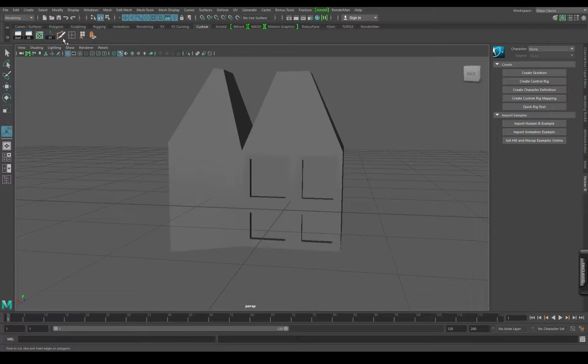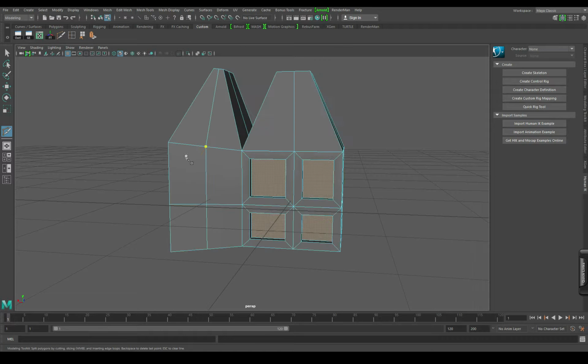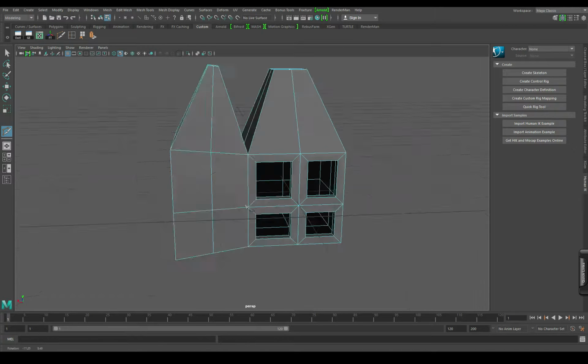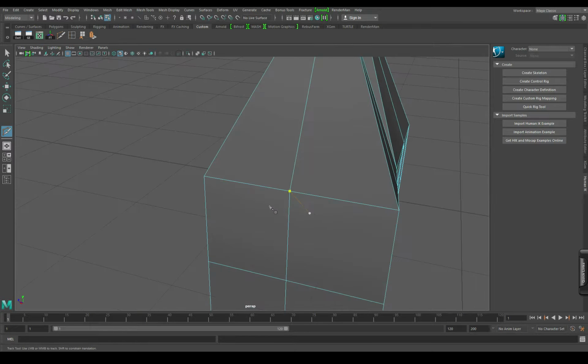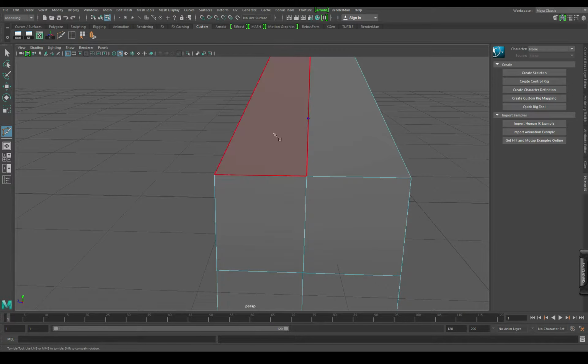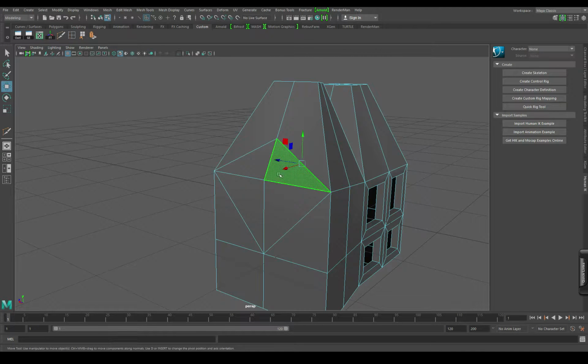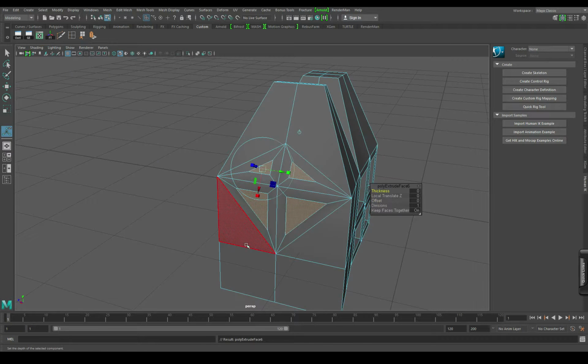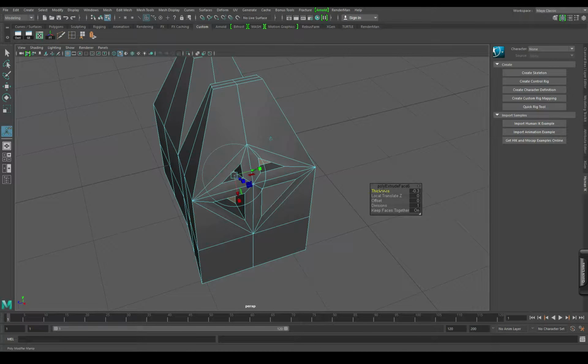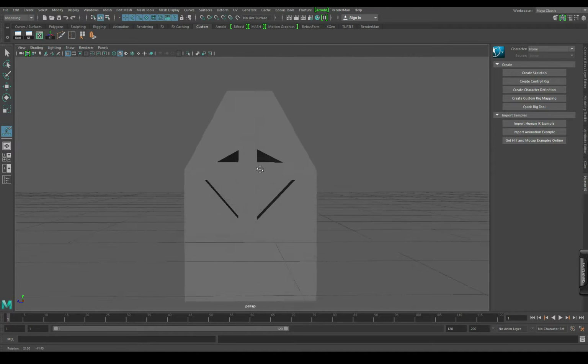And then the multi-cut tool. So this is the last one we want to cover. If I select my house again, and I want to make my own cut, I can do that. I can select whatever highlights. I can click on the edges and start cutting my polygons the way I want them. Okay. I can add new things, and from there I can go in and do the exact same, extrude, offset a little bit, hit extrude again, and well, you get the gist of all this. Okay.